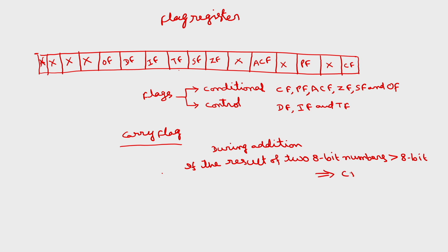Set means 1. If the sum of two 8-bit numbers is less than or equal to 8 bits only, then the carry flag will be reset. This is set and this is reset.